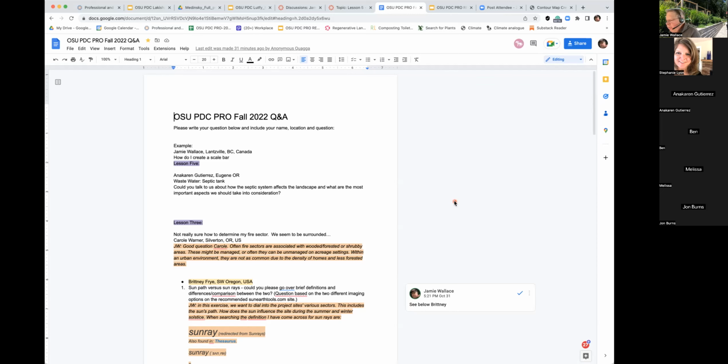Right. Well, it's a good question. We have a septic system on our property, and you definitely want to have a few considerations with those. The main thing is septic systems rely on evaporation to operate properly. So you want to have some sort of vegetative cover on the field, and most often that's perennial grasses. And I'm sure that's what you currently have.